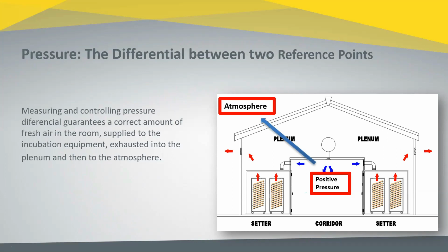When we talk about managing exhaust plenums, we have a negative pressure by desire, and therefore we have a negative plenum that references back to the room. And that's the normal recommended way of referencing these points.